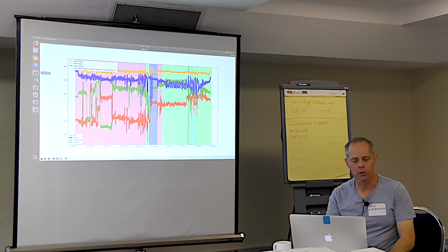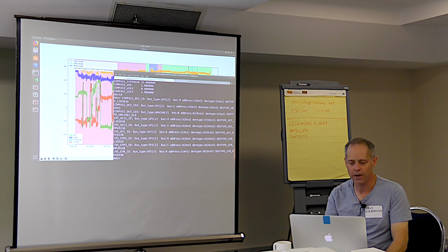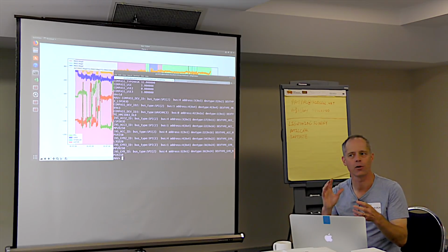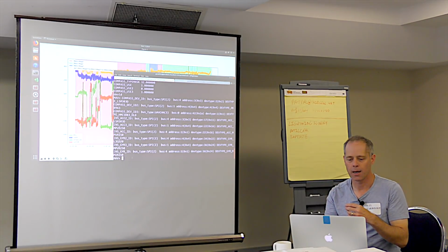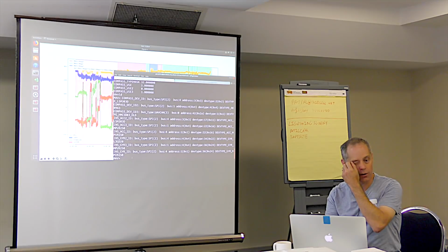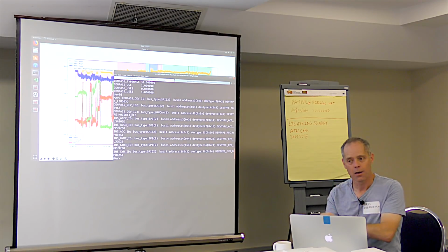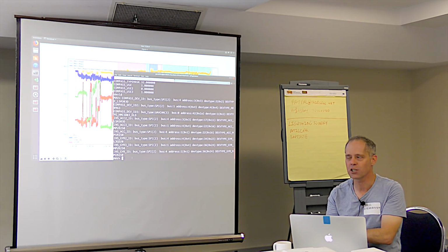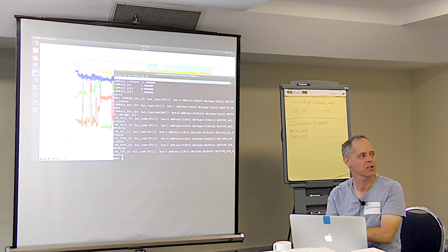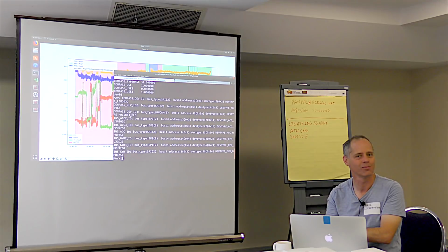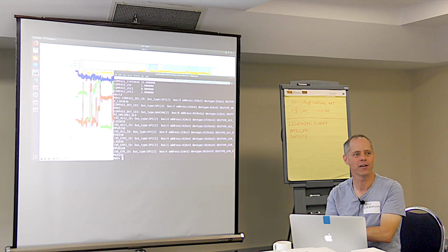There's another thing that you can look for, evidence of a problem with magnetometer rotation, if you have an inconsistency. Now I have one log here where one of the IMUs was actually rotated incorrectly on the board, which is a very interesting log.